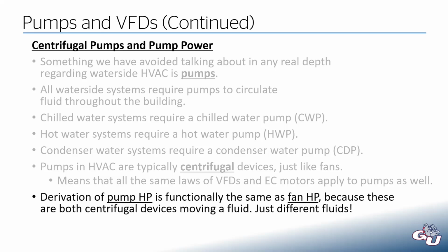The derivation of pump horsepower functionally is the same as our derivation of fan horsepower. And I didn't walk you through how we arrived at those fan horsepower equations, but when we look at how the pump horsepower equations are built, you're going to see a lot of similarities, a lot of the same DNA as compared to the fan horsepower. And that makes sense because these are both centrifugal devices, fans and pumps. They're just moving different fluids. One is moving water and one is moving air.